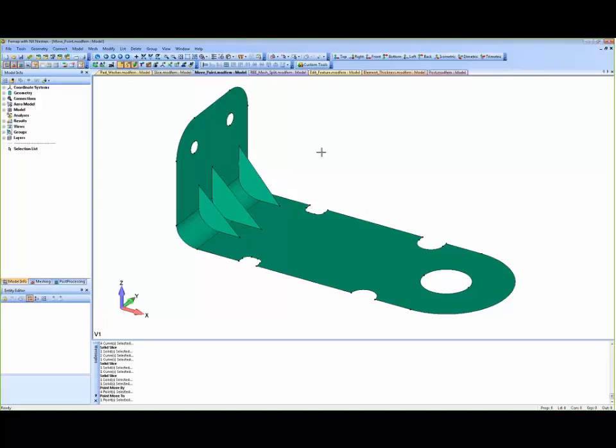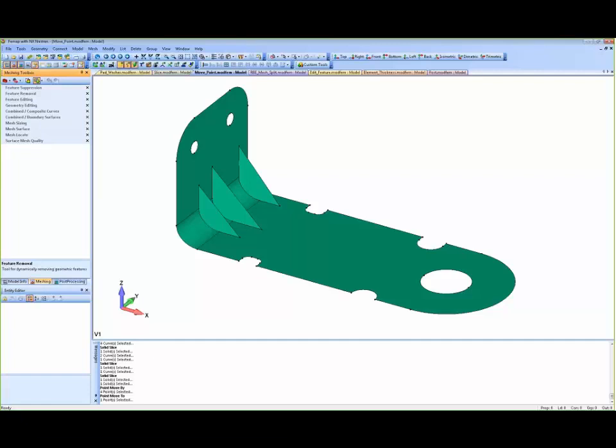The development team has also added some defeaturing tools, or some enhancements to the defeaturing tools, one of which is in the meshing toolbox. It's going to be in the feature removal. The loops, curves, and surfaces options were in there in Femap 11.1, but now they've added blends, and they've also enhanced this curves option. So I'm going to select curves, and I'm going to use the selection button, select that curve there, throws that out. I'm going to select this blend in the corner, it throws that out.